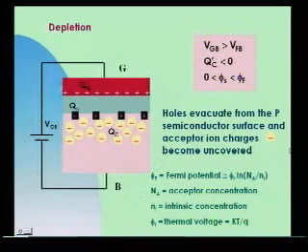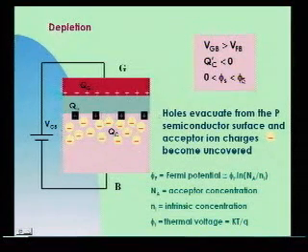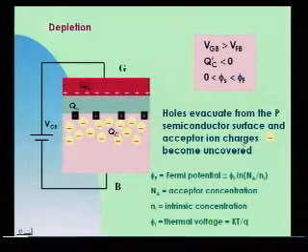In this situation, the surface potential, that is the potential measured here in the interface, is positive, but is less than the Fermi potential. The Fermi potential can be understood as the contact potential between the doped and the intrinsic semiconductor. It's not that there is a junction like that here, but the concept of the Fermi potential is like that: the contact potential between the intrinsic and the doped material.